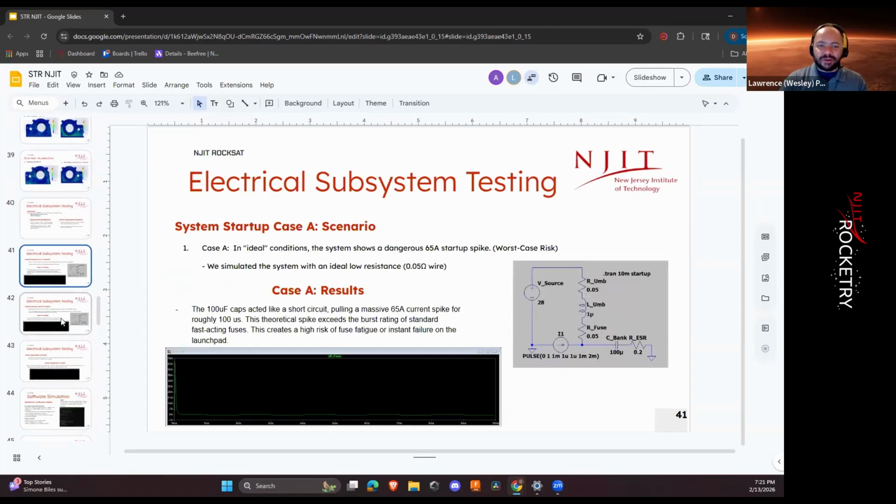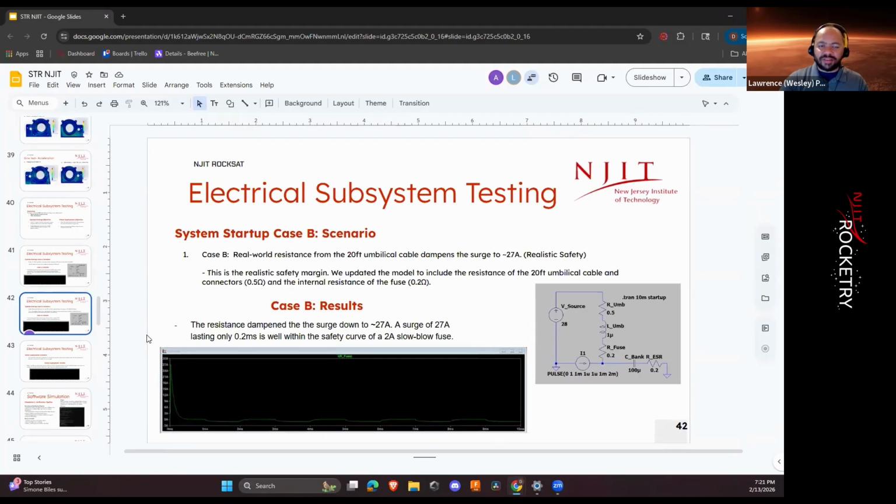Noted that that's only 200 microseconds, so my concern immediately fell. Very low risk, but I do understand the risk analysis you are doing here as far as trying to mitigate any fuse wear, any trips. This is very, very not likely to trip the polyfuses on the vehicle.